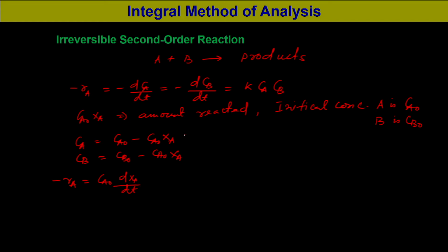If we differentiate this expression, dC_A/dt would be equal to minus C_A0 dx_A/dt. So, if we substitute here minus dC_A/dt, C_A0 dx_A/dt in this expression,